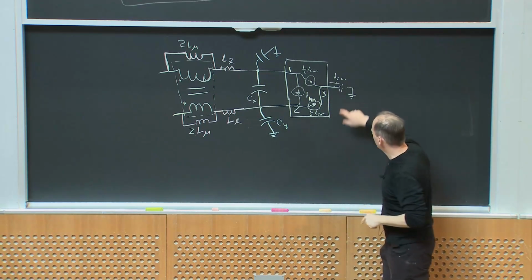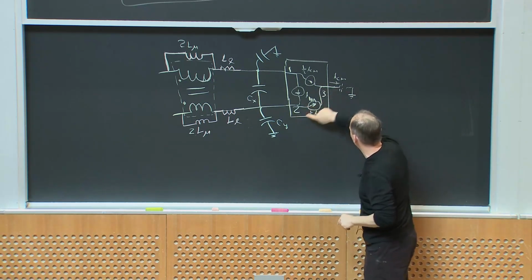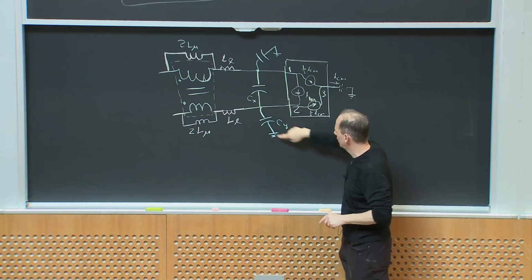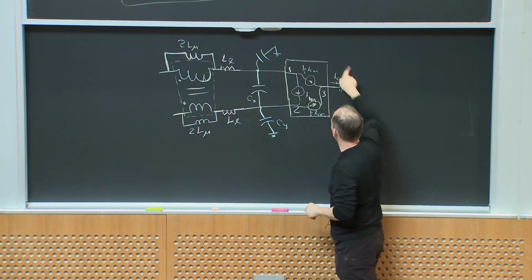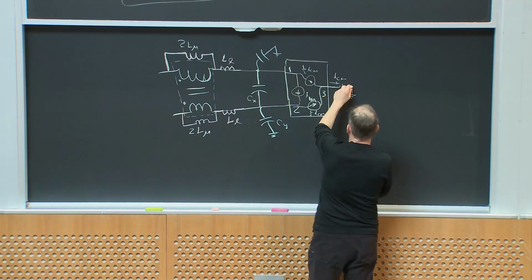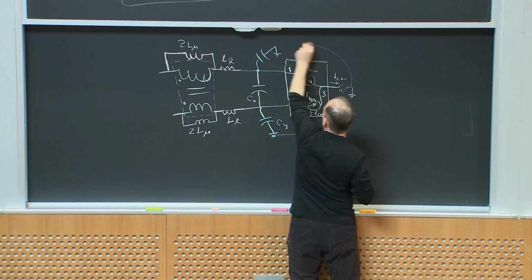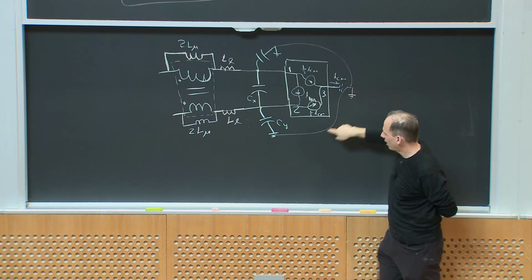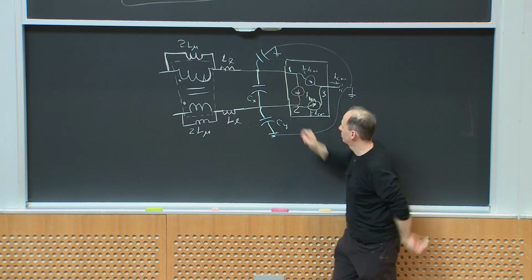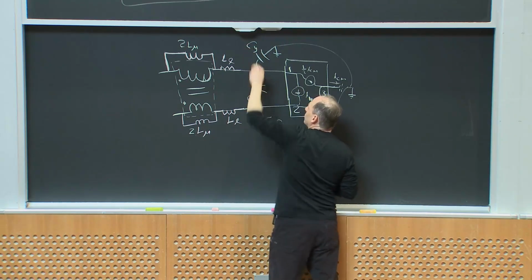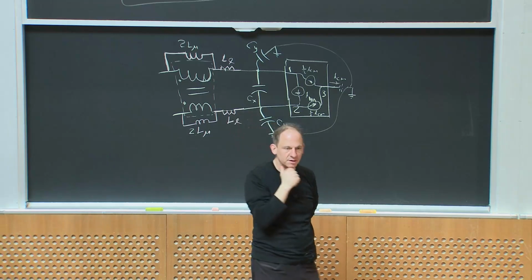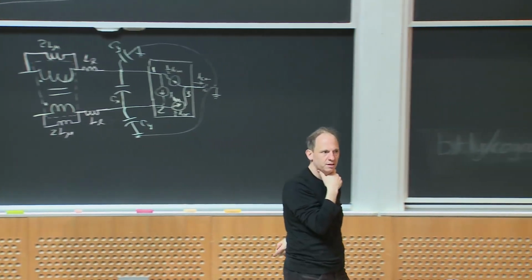So what you'll see is, half the CM current could come through here, come up through this capacitor and happily circulate there. That's a low impedance capacitive path at high frequency. Same thing here, it can circulate this way, right? Because these guys are connected. Okay? And so the current at high frequency wants to go through the CYs, but doesn't want to go this way because of the high magnetizing inductance. Does that make sense, everybody?